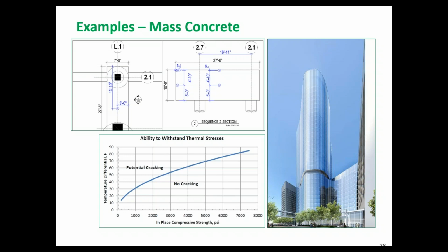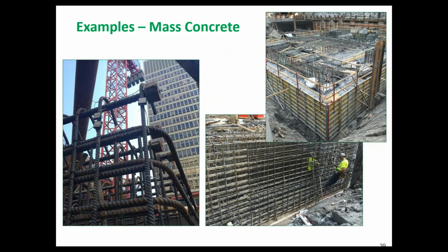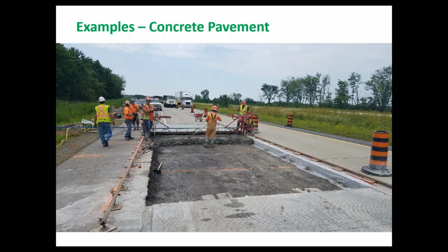And that's something that you can work out and basically leverage to minimize the duration of heat curing or keeping the concrete cool in the summertime. And again, this is another set of pictures where you see how sensors are installed in mass pours. You can install them the day before where you have heavy caging, and the next day you would pour concrete.